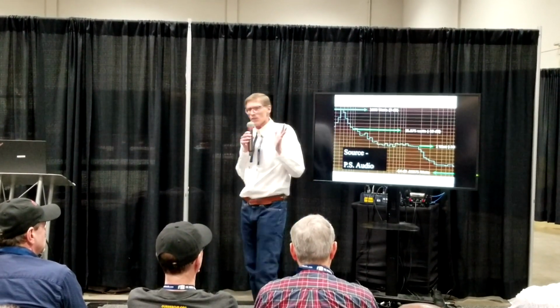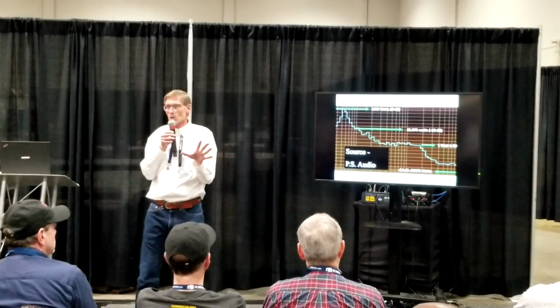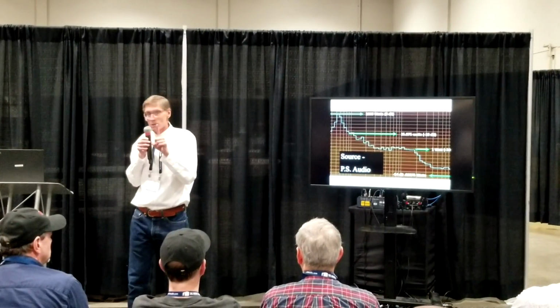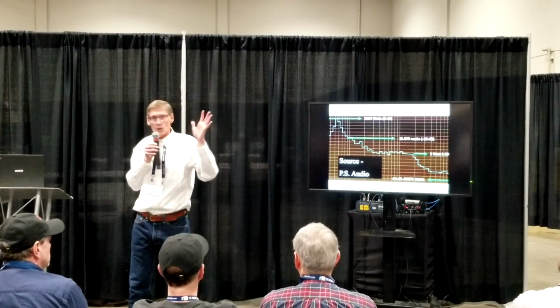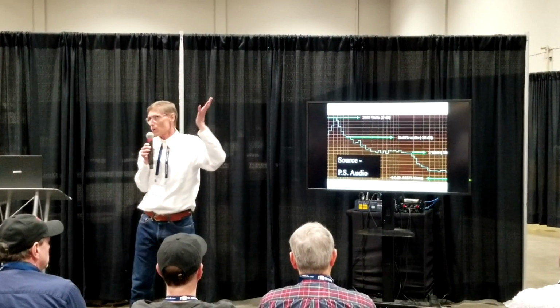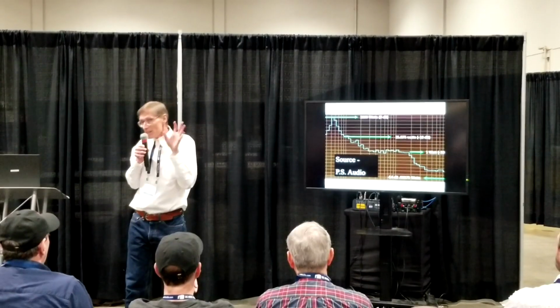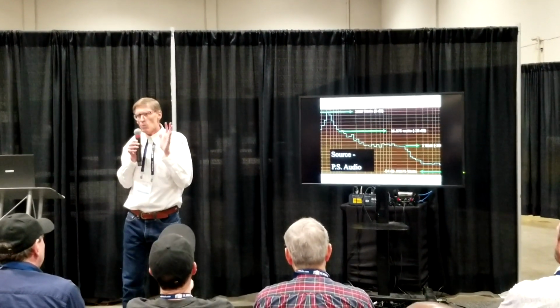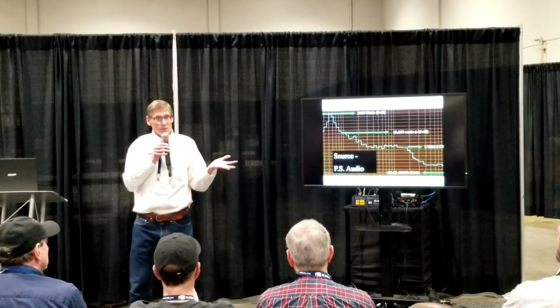We got a ton of power at the low frequencies, and we're trying to jam this through a cable into our speaker. And our speaker is what? We just learned our speaker cables at the low frequencies are a pretty high impedance, right? Certainly not even close to 8 ohms. They're in the hundreds of ohm range. Yet at the same time, we're trying to put the most power into the load at that frequency with the largest mismatch.